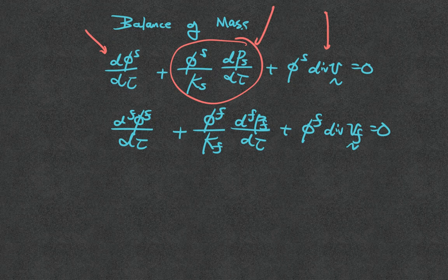Now, if the material is incompressible and undrained, then what happens? If the material is undrained, all the possibility of water getting out is taken out, so there is no relative velocity, so I'll cancel off this term. Then what happens to this problem is that the system becomes an ODE.